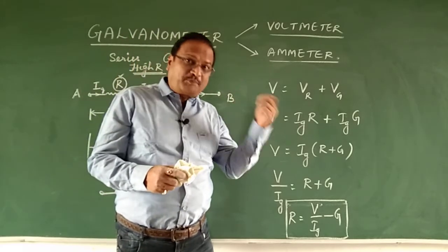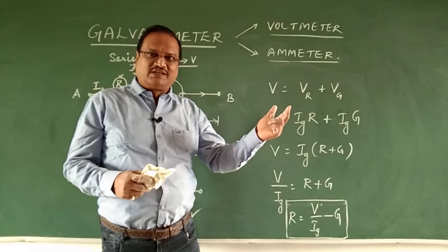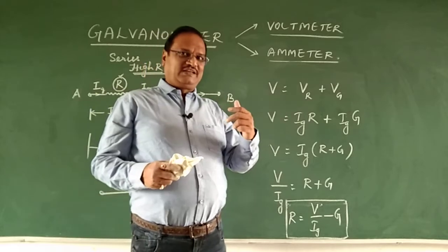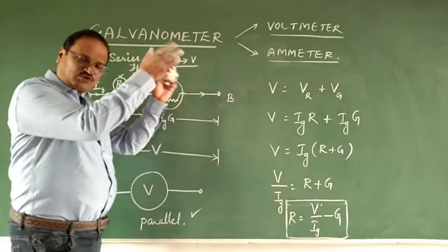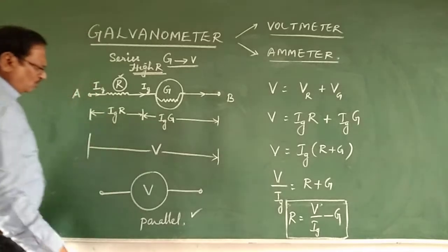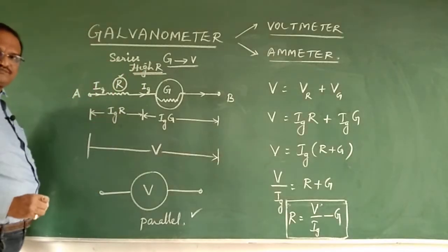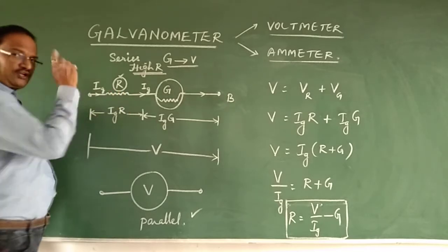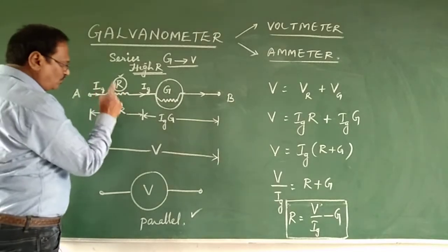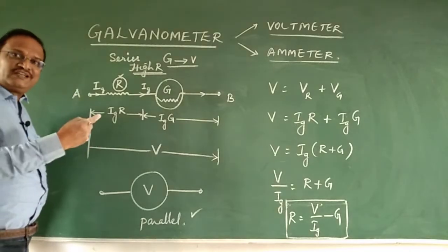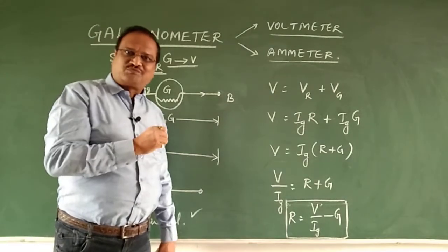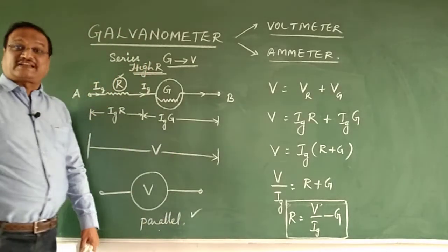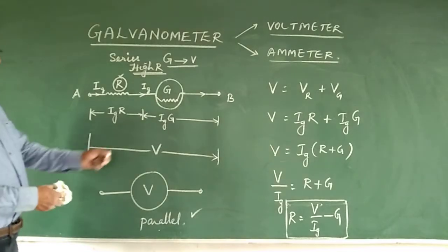When it has to measure a potential difference, it cannot absorb or deviate current. It cannot do anything with the outside external current. It already has high resistance. If it also consumed current, there would be a dissipation of energy or a voltage drop across this resistance, and then the measurement would not be correct. So you have to connect a voltmeter in parallel in a circuit, as you can study in Ohm's law.